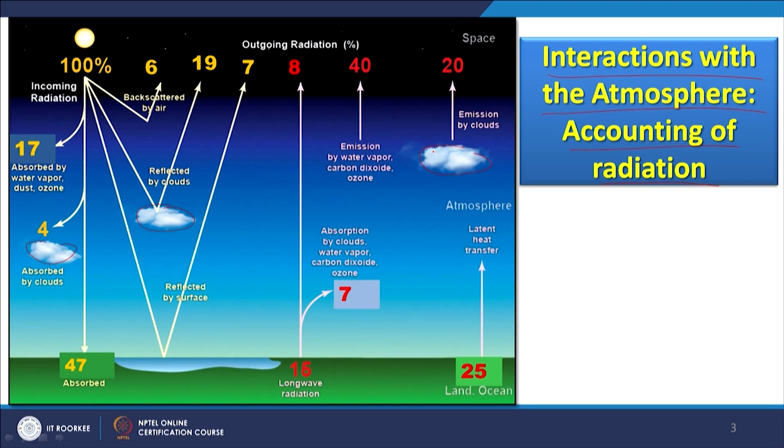So, when we go for emitted or thermal infrared, clouds also play an important role. Thick clouds can be detected very easily, but when you have a very thin cloud or haze, your images become unclear, and removal of such effects also becomes very challenging.